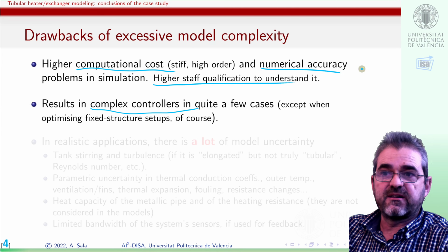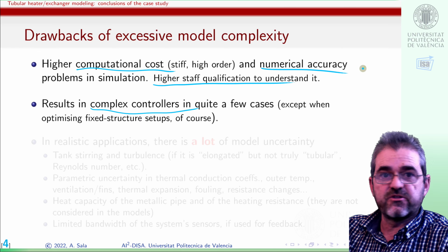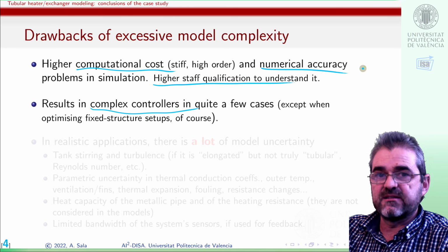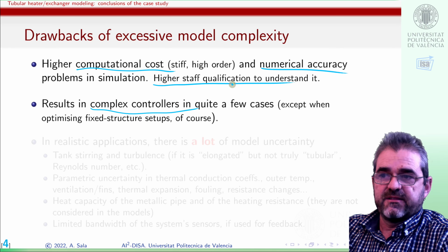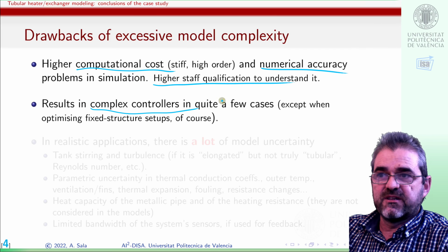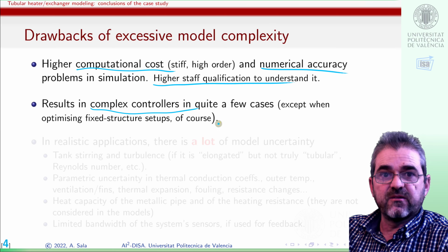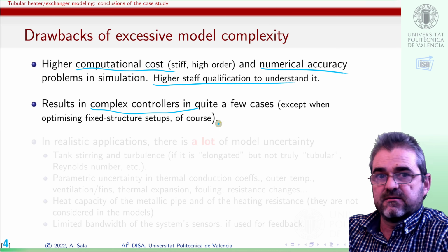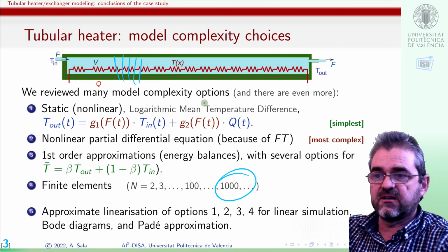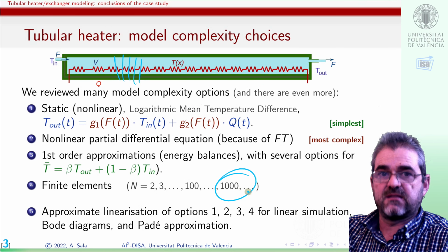In fact, numerical accuracy of the matrix computations to compute pole placements, observers, whatever, may render those computations useless, accumulating numerical errors. And even if they work, a technician controls this thing with an all or nothing controller. If the water is cold, switch the heater on. So how the hell are we discussing using a model with 1000 states?